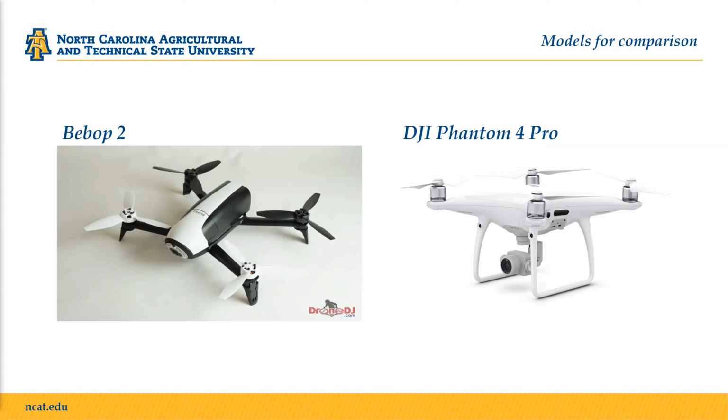Skyjack disconnects the controller by changing the SSID and immediately reconnects, and is then able to transmit commands through the malicious drone to the hijacked drone, enabling it to take control of another drone in flight using a customized script, thereby forming zombie drones. The DJI Phantom 4 Pro is not vulnerable to this attack, where the Bebop 2 drone is. Maldrone sets up a proxy serial port, intercepts flight commands from the controller, and redirects actual serial port communications to fake ports while forwarding the hijacker's commands to the drone. While the Bebop 2 will be affected, this attack is not applicable for the Phantom 4 Pro.